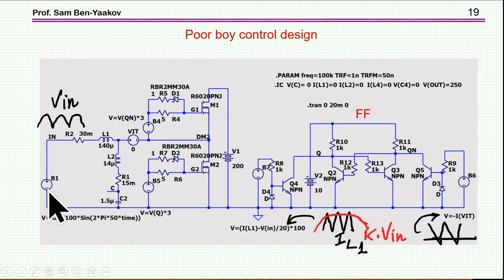Again, I'm using here a rectified input. In reality, we don't actually need a rectification, because we can use either a full bridge here, I'll show it later on, or a totem pole, which gets rid of the diodes here, or the rectification. So it's a diodeless realization. But this is again just a demo, so let me just go over it again. We have an AC which is rectified. We have the peak current here, which is the low frequency following the input, okay? And again, in order to simplify the control, I've put here a DC.